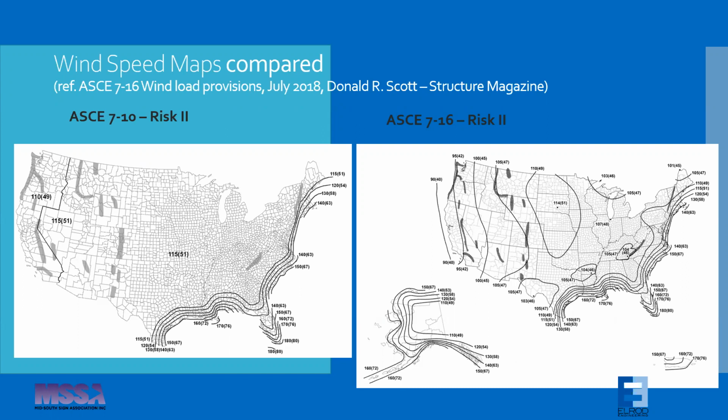On the left side of the map, pretty much everything is 115 miles an hour on the interior. But if you look at the right, much of the inland area, especially through the Midwest, is 107 miles an hour. That may not sound like a lot, but that can make a difference in your design as to what size through bolts you need, what attachment methods and things like that. The way we view it, the lower the wind speed, the more efficient we can make your design.